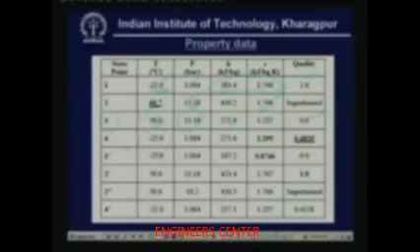Point 4, okay, it is the exit of the isenthalpic process. So, the enthalpies are same at point 3 and point 4, which is known to us, and we know that the temperature is minus 25, which is same as the evaporator. Pressure is now also known to us. So, from this we can find out what is the entropy. Okay, and you can also find out the exit quality from these enthalpies. And point 1 dash is saturated liquid at evaporator temperature. So, you can find out easily enthalpy and entropy.